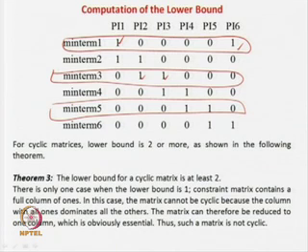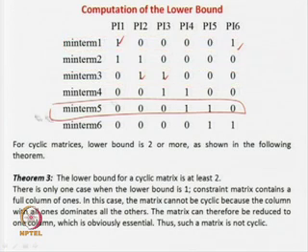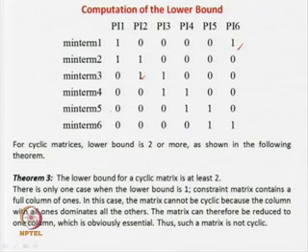So, if you have to cover min term 1, 3 and 5, 3 columns will be required. For example, if you take PI 1, it will cover min term 1; if you take PI 2, it will cover min term 3; and for min term 5, you have to take another PI. In other words, 1, 3 and 5 are all column disjoint rows, or independent rows.